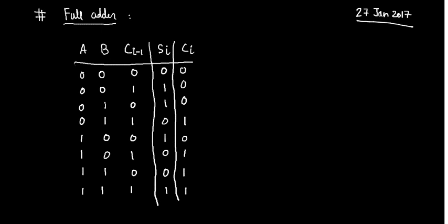Given certain specifications, say for example our specification is simply to add A plus B. The procedure remains the same. We draw the truth table, take function by function, draw a K-map for each and every function, minimize it as small as possible, and then realize it. So if you draw the K-map for this,